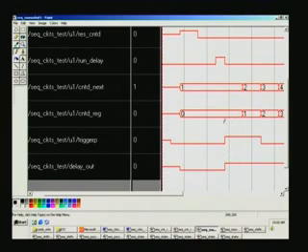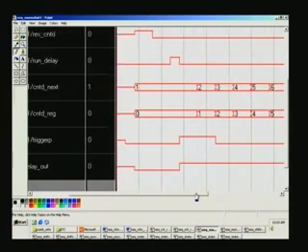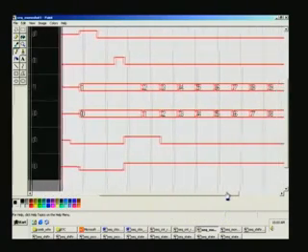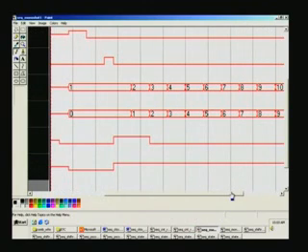But this is corresponding to this 0 here. 0 itself is spread over a 1 clock pulse. So in other words, last one was 254 plus 0, if you add, you have got 255 clock cycles delay. That's what you have got. This proves that whatever is the setting, you get precisely that, right? And now another point is, suppose earlier I said 256 cycles.